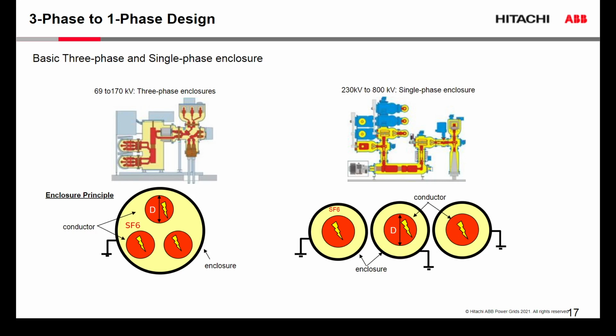So there are no real limitations, other than that the distance between the conductors is designed to the phase-to-phase voltage. That means at a certain voltage level it becomes not very handy to handle such large compartments on site, assemble them, seal them, and assure safe operation. So that is one of the reasons that this technology is usually used for the lower voltage levels.